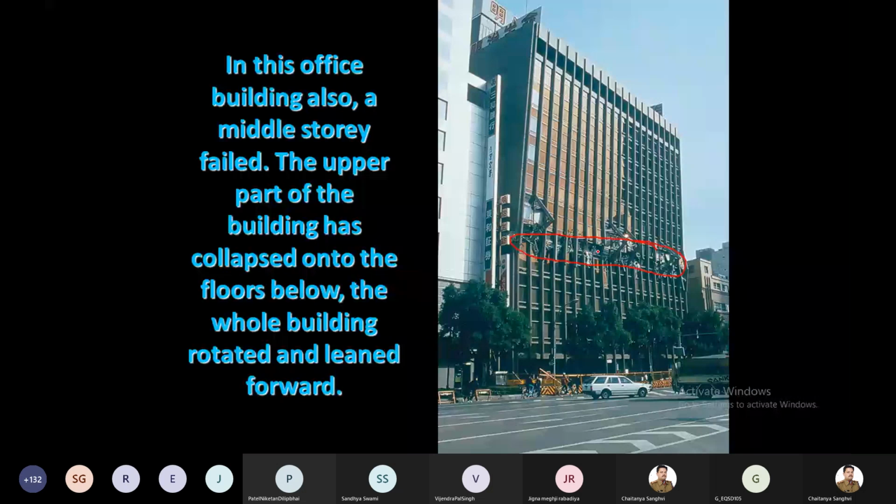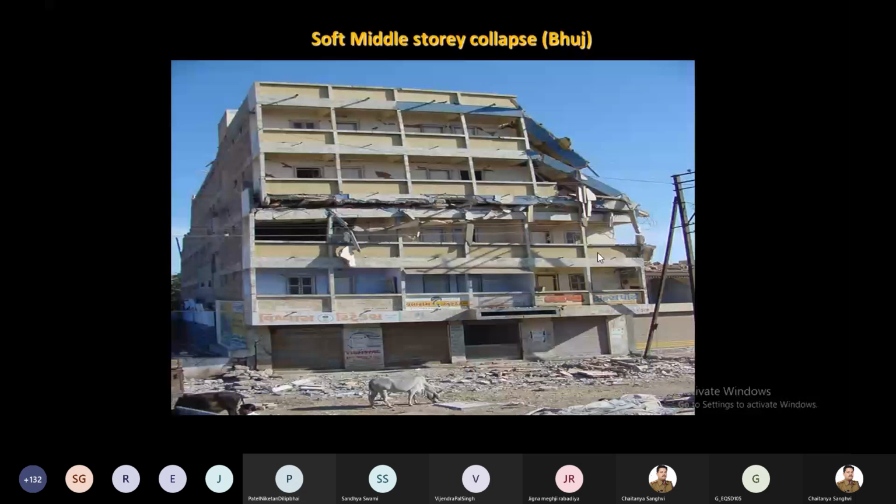And I told you again, within 2 minutes the earthquake is going to identify this deficiency. An earthquake can reach any floor within 2 minutes, I tell you. And I think this is where intermediate soft story failure has been observed. Here also you can see, it was actually an open ground story, but what happened? The builder constructed shops illegally after the construction of the building. So the soft story was avoided on the ground story, but there was a soft story on the upper part, and immediately it was identified. This is gone, right?